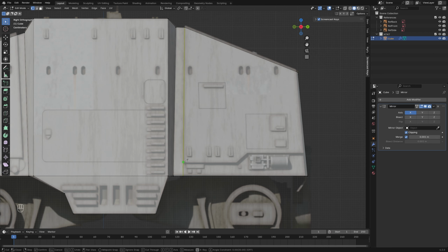to activate the knife tool, and put the cursor right here, and press Y on the keyboard and left click when you reach this edge here, and press Y 2 times and set another left click and press Y once again to move it back.